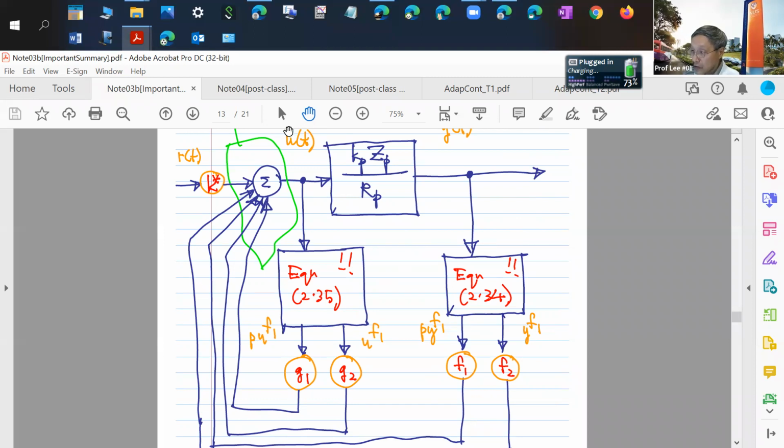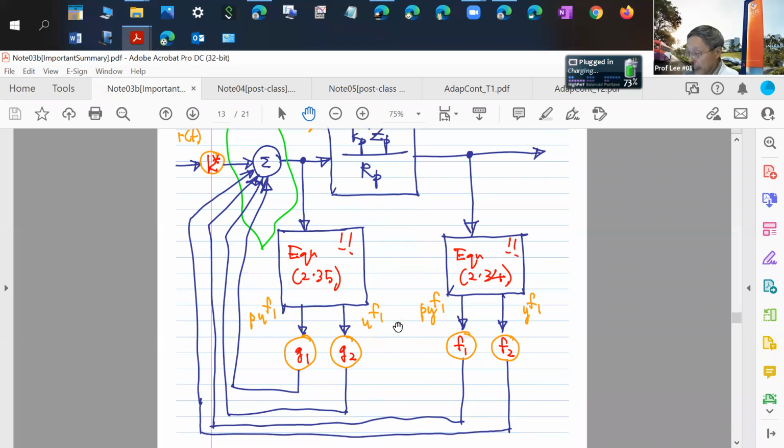You take U, pass it through the 1 over T, set up in controller canonical form. Again, these are the two signals exactly available coming out of your state variable filter. So they are there. Now look carefully again. For your perfect control law, if you knew the system exactly, you can calculate exactly this number F1. You can calculate exactly this number F2. You can calculate exactly this number G1. You can calculate exactly this number G2, right?